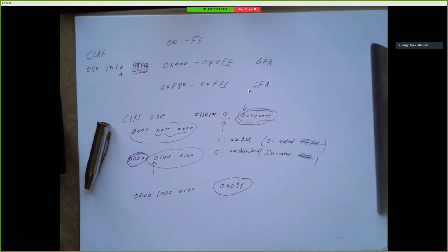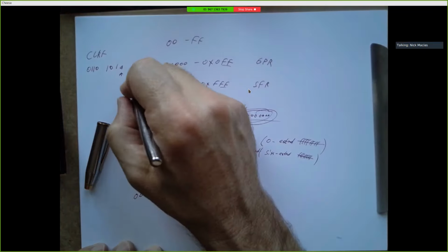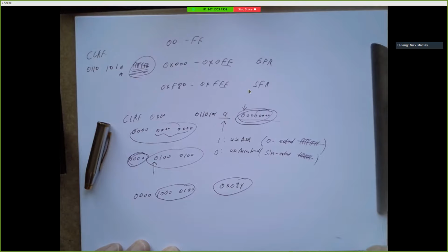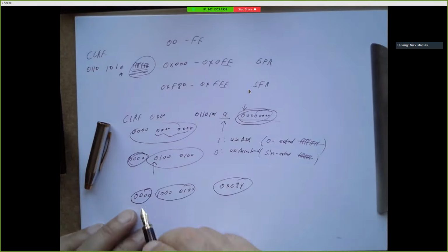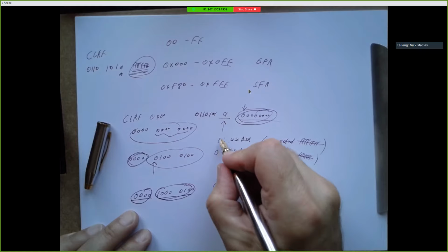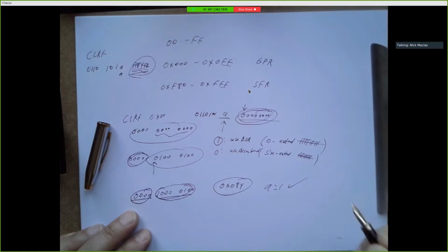So we're trying to clear 084. Well, this is going to be our value of F. That's going to go in these 8 bits of our instruction. But we want the upper 8 bits to be 0. Now, if we 0 extend this number, we're going to get 4 zeros, and then an 8, and then a 4. So using A equals 1 is certainly going to work.